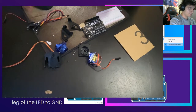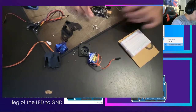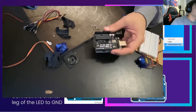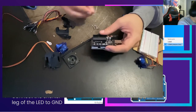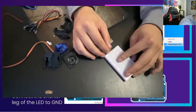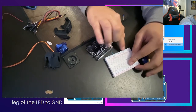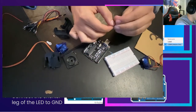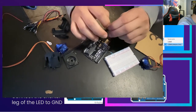So we connect the, well, first of all, we leave that there. We're going to go to the Arduino. As you can see from the presentation, we're gonna put one end of the resistor to pin 13. Alright, and then the other end we're gonna put it to a breadboard. Now if you've never used a breadboard, it's pretty simple. Essentially all this row right here and this row right here are connected with an electrical plate, which allows you to have different connections that are transferring the signal, or an electric signal.